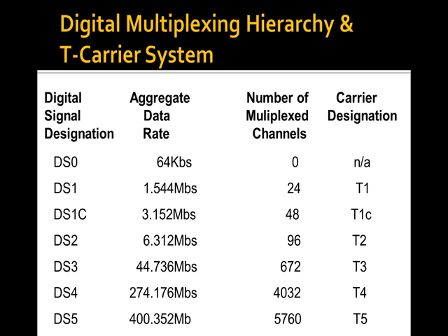I'm not decoding the actual signal on the wire. I'm just looking at the value of the bits to determine what the signal was. Remember, this is coded. Induced noise simply never gets decoded. I can wipe out data, but that's not the same thing. Okay, so we've solved that part of the problem. Attenuation and noise pickup have been addressed.